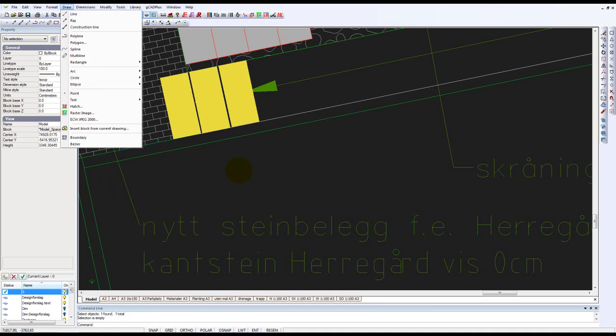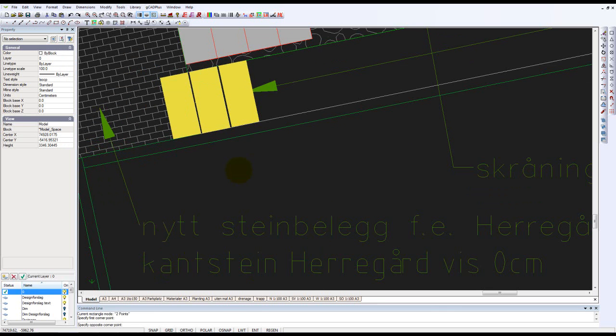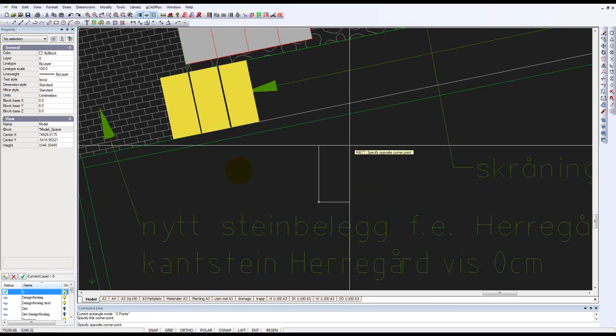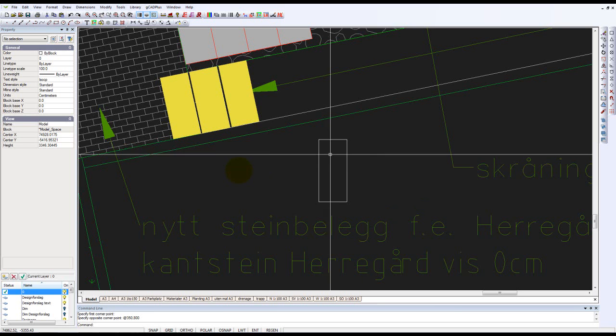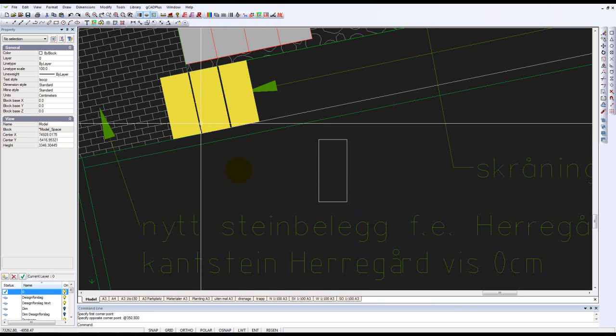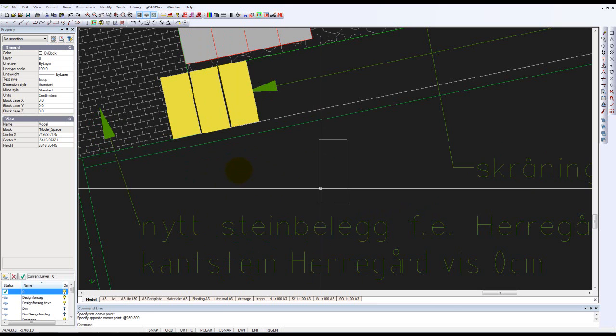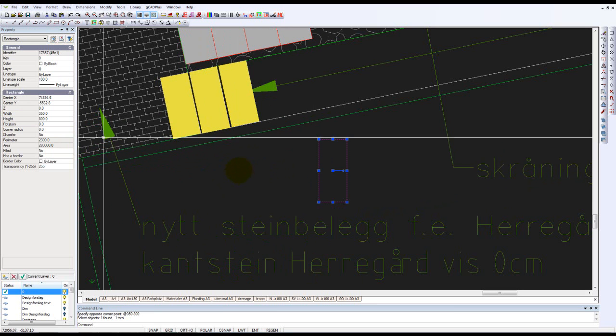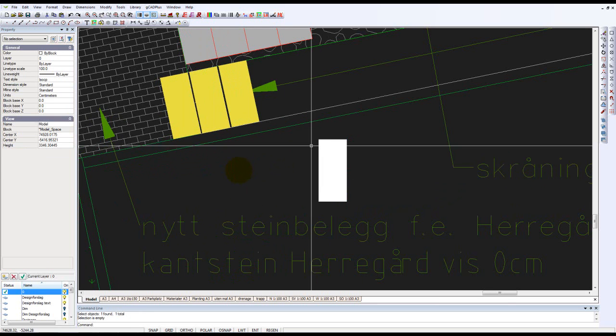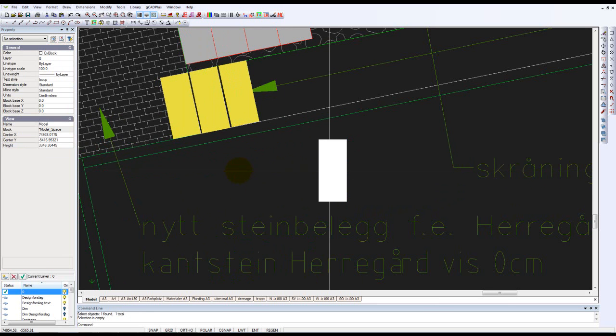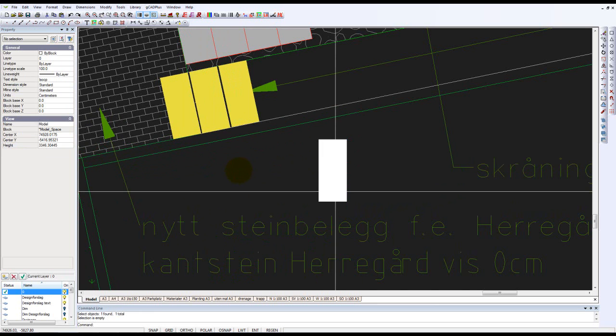Now that we know its size, let's use the rectangle command and draw a new rectangle. I'll click here and then move away and use the notation 350, which was the distance in the x, comma 800, the distance in the y. So now we have a rectangle the same size as that block. We could apply a fill to it. Let's do that. We won't worry about color, but we have a filled rectangle, which is a very simple shape, takes up very little space.